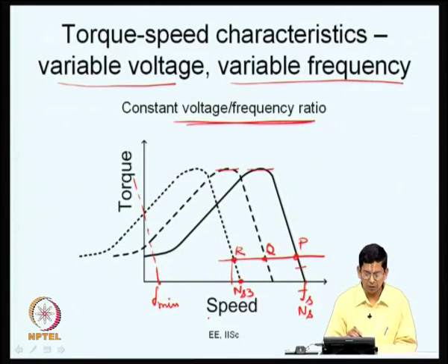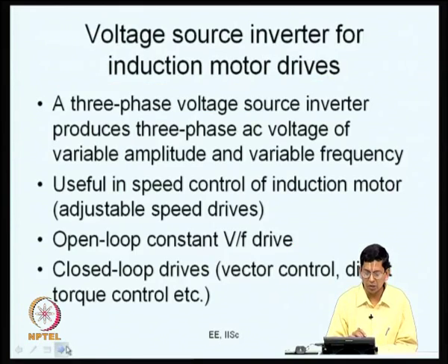And also you have several closed loop drive schemes, which as I mentioned in the previous class will be dealt with in other NPTEL courses exclusively on the subject of motor drives. That is an involved subject. For example, if you want high dynamic performance, you have drive schemes called vector control or field oriented control and direct torque control, etc. These require an understanding of how you model the machine for dynamic operation, and how you go about controlling them in the different frames of reference, etc.